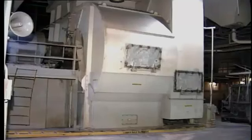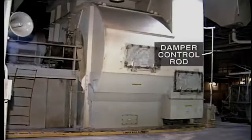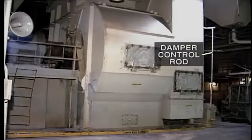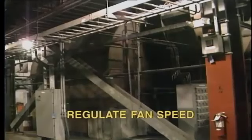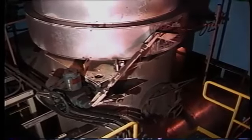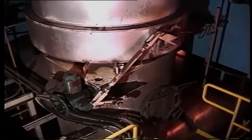The conventional way of adjusting forced draft is to adjust the opening of the inlet damper supplying air to the fan. The discharge damper is normally used for isolation only. Another adjustment method is to regulate the speed of the fan. Control is normally effected remotely and generally automatically, as we'll see later.